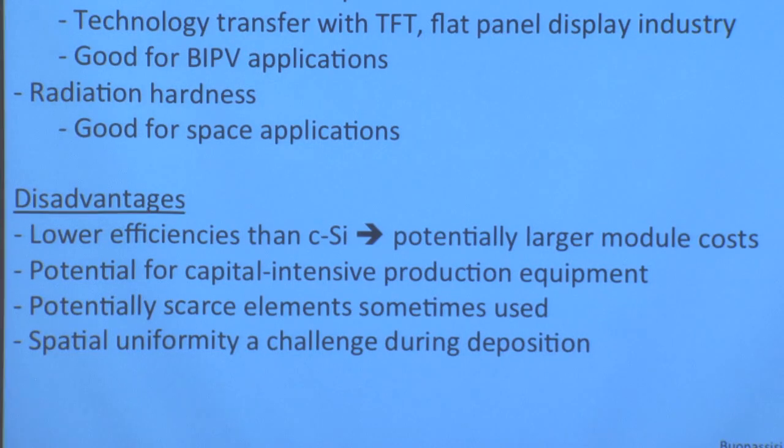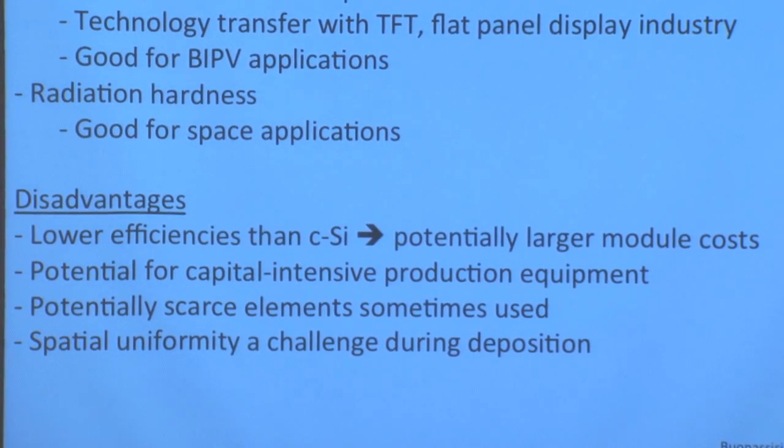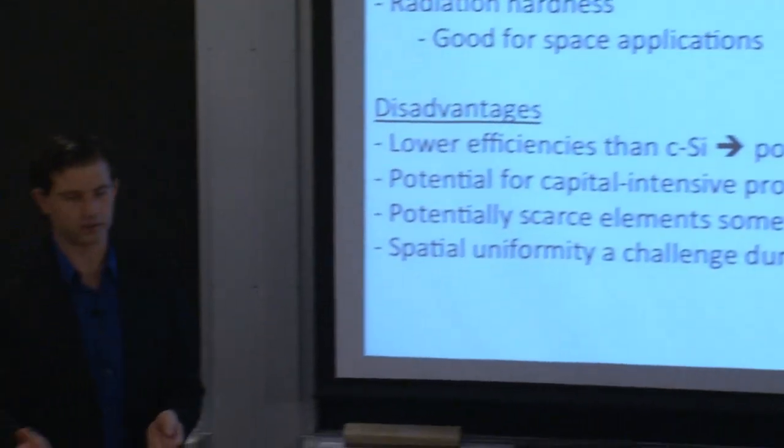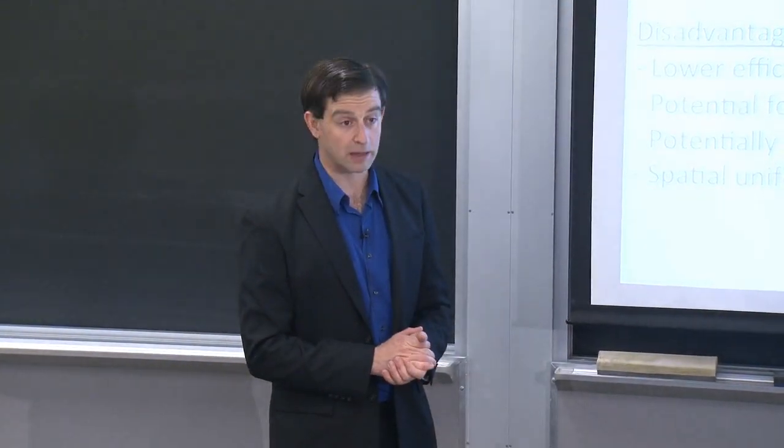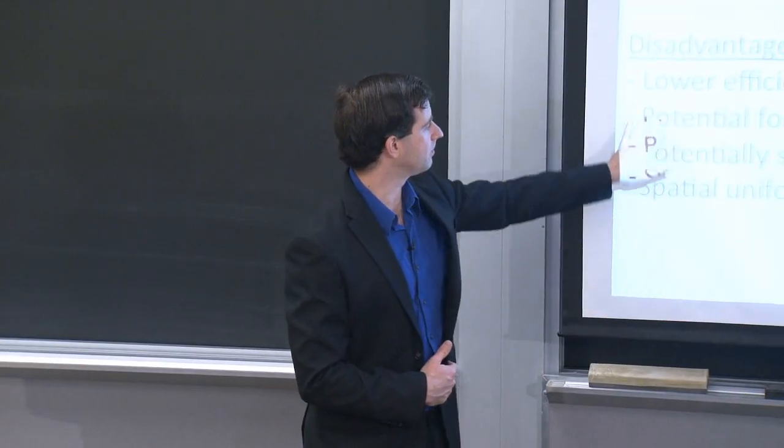So at some point, if you look at the cost of the material versus efficiency, you start entering negative territory. If you're producing like an 8 or a 7% module, typically, you would have to pay your customer for them to accept your module. So you really have to achieve a minimum efficiency target to be cost competitive. And as a rule of thumb, that's typically 10 to 12% for today's costs of glass, encapsulants, framing, materials and labor and installation, and so forth.